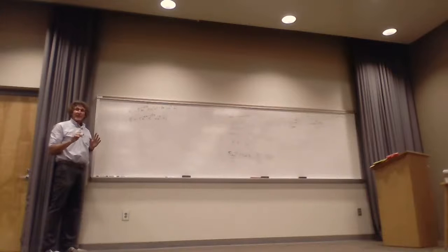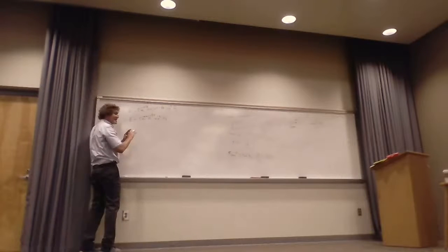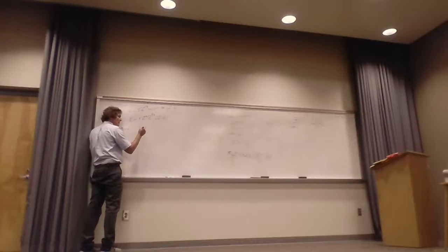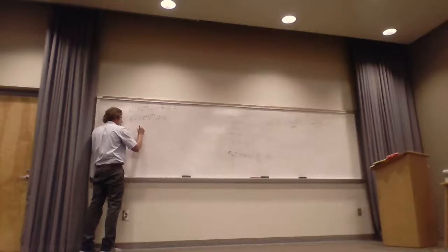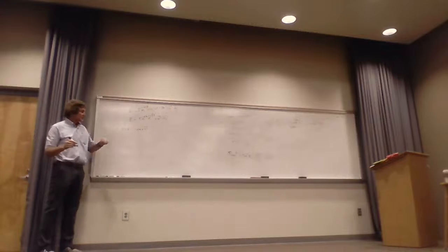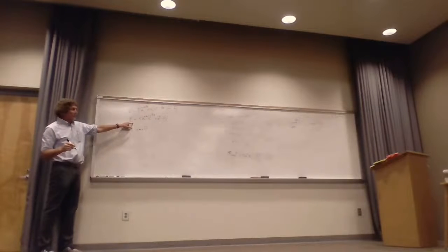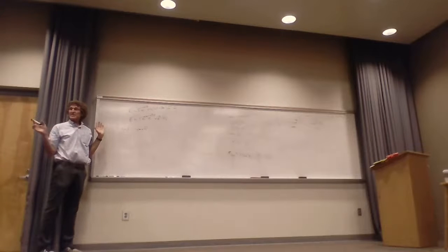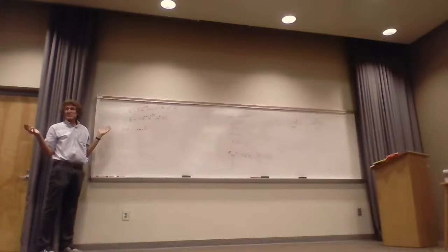Now, here's the trick to get H easily. You can say that I can take the curl of E and set it equal to minus dB/dt, or really minus j omega times mu times H, and we could solve for H by taking the curl, couldn't we? Y'all see we could take the curl of that, and then divide it by minus j omega mu, and we could get H. That's a pain. I mean, that's the way you do it in general, if you don't know.